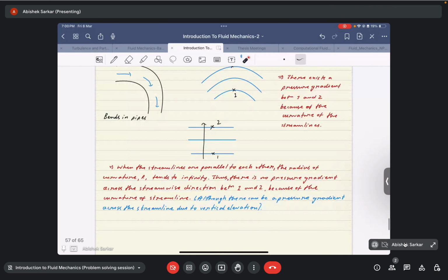Again, if the streamlines are parallel to each other, the radius of curvature r tends to infinity. Thus there is no pressure gradient across the streamwise direction between 1 and 2, because the curvature of the streamline is infinity.